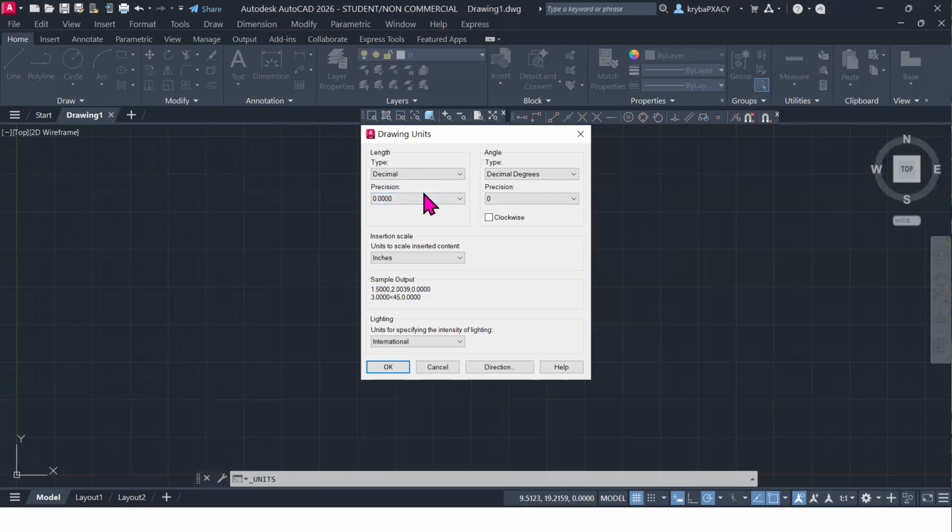So when we put our values in, we're going to notice that there's going to be decimals or not. You can put as many decimals as you want. Accuracy-wise, AutoCAD holds, I think, up to 13 decimal places, although you're not going to show that for everything that you have. So depending on what you're interested in, I like to stick around 4. I think that's pretty good. You could put in 5 if you wanted to, or less. But for the most part, for English units, especially if we're converting from fractional, 4 can do us pretty good. Okay.